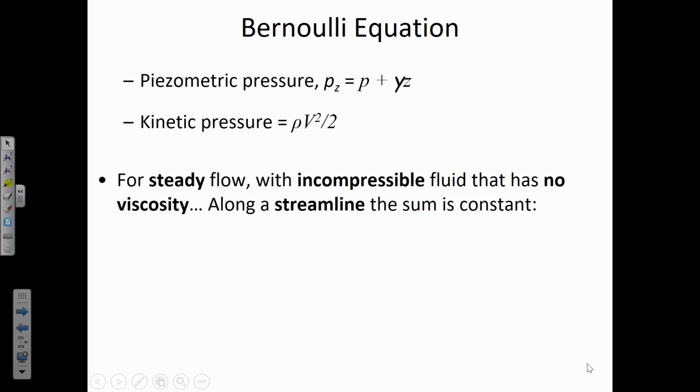Okay, now in this nozzle, between location 1 and location 2, what has higher velocity? Location 2 has the higher velocity. How does it have higher velocity? Like, where is that energy coming from? Well, let's look at the elevations. Between 1 and 2, there's a little bit of a change in the z, but not enough to account for the velocity being so much faster at location 2.